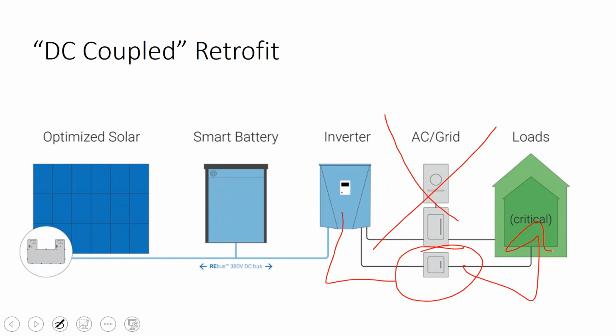I'm a big fan of powering the entire home. I don't like critical load panels because, to me, if I'm doing an off-grid house and the battery bank gets low, I'd rather we manage the energy through being smart about our appliances rather than protecting it with a critical load panel. But that might not be the same if you only have a really small battery and you just want to make sure that the air conditioning, the garage door, and the refrigerator stay on, and maybe a couple power outlets to plug in, and that's it. A critical load panel may be all you need. And so maybe you don't necessarily need a transfer switch if the inverter has a separately derived critical load panel, where a smaller transfer switch would actually be built into the inverter itself.